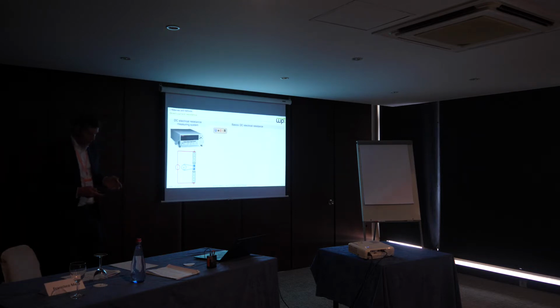First I need to choose a characterizing measurement system or method, and I chose the electrical resistance measuring system for this presentation. I used a source measurement unit and a nanovoltmeter, shown here, from the company Keithley. With this measurement unit, on round specimens, I applied the current at the front, and in the narrow space of the specimen I applied the voltage measurement.